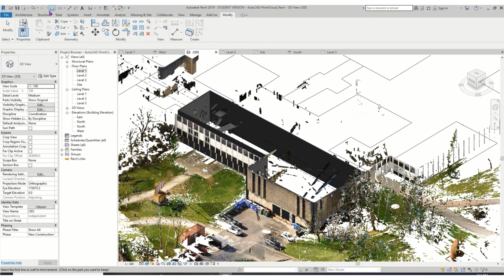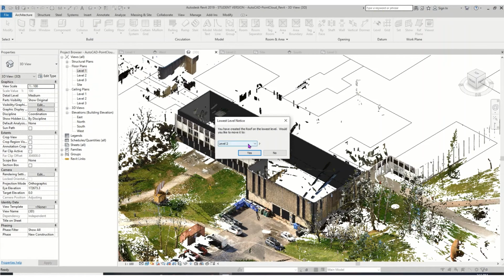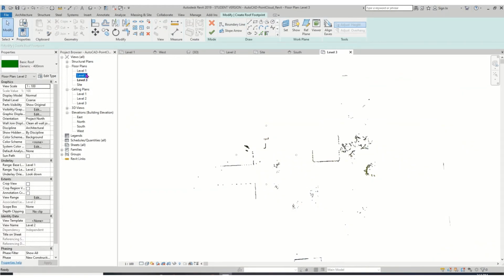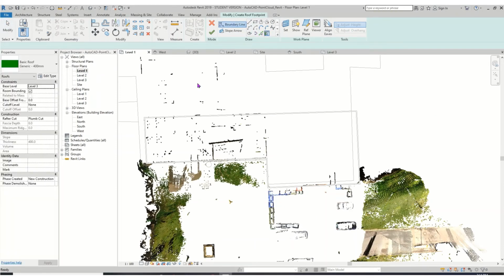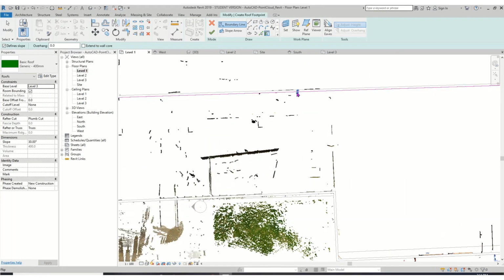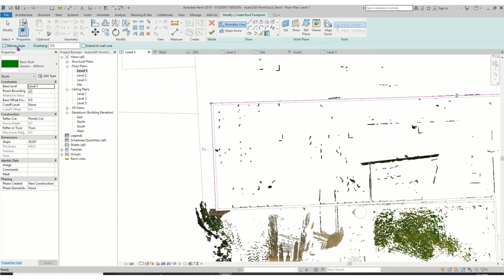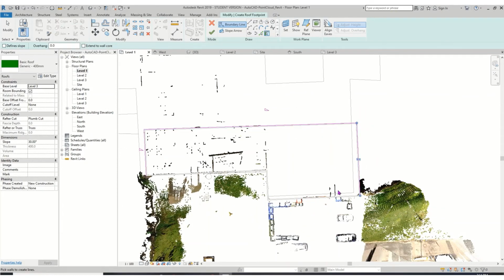So what else we can do is to maybe create a floor, but let's do a roof because it's quite the same. I want it to be on level 3. Yes. So now I will go to my level 3, level 2 maybe, and I will just choose the walls. Here first flip to the external layout, and then I don't want to define any slope, so turn off the define slope. I want a flat roof.